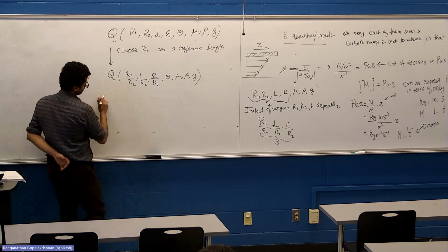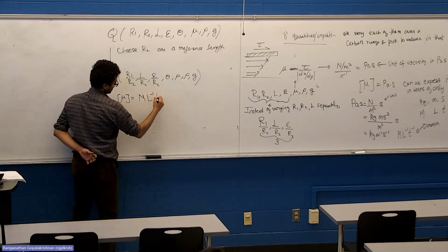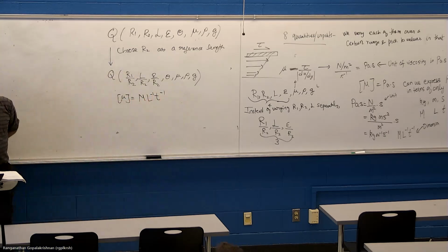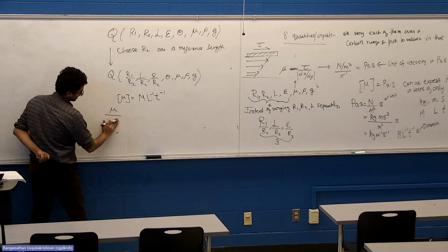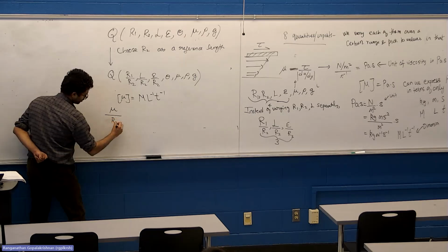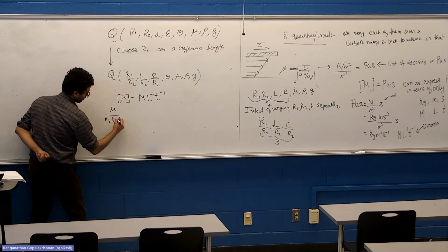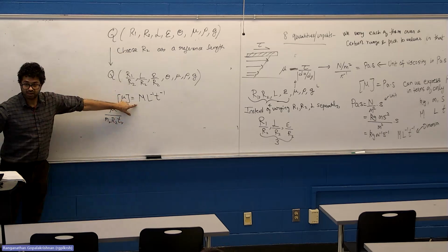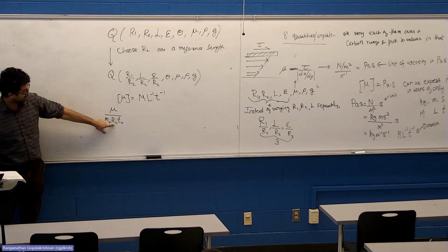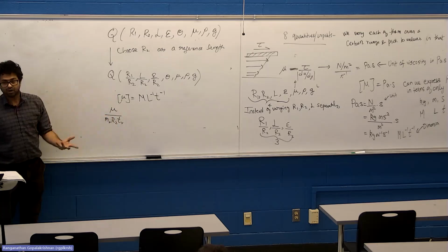So I just told you the dimensions for viscosity are mass per length per time. So if I want to express viscosity divided by something else, that something else cannot only have R2, it should have some reference mass, it should also have some reference time. Because the dimensions need that. Right? You can't form viscosity with only length. To form viscosity, you need a mass, length, and time in some combination. Do you agree with me on that?